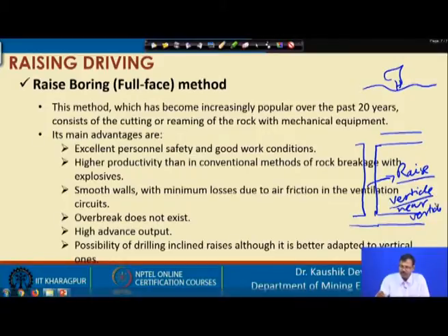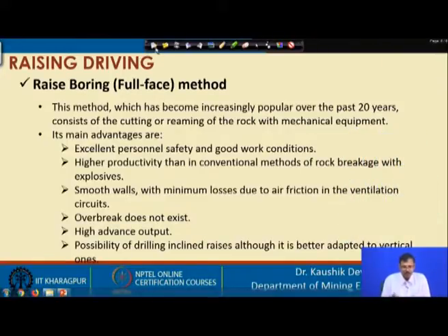So, basically raising is the access way between two levels in the underground, and raise boring is a very popular method, because again just like shaft sinking, raise boring takes a little bit less time if you are comparing with the manual method or conventional method where drilling, blasting or this type of unit operations are being carried out.